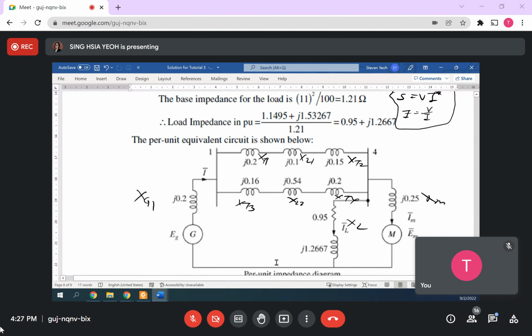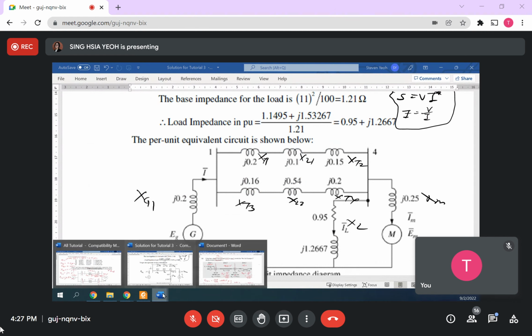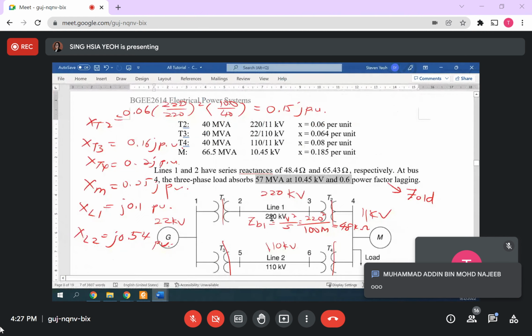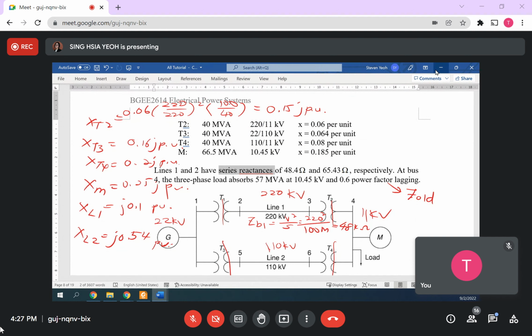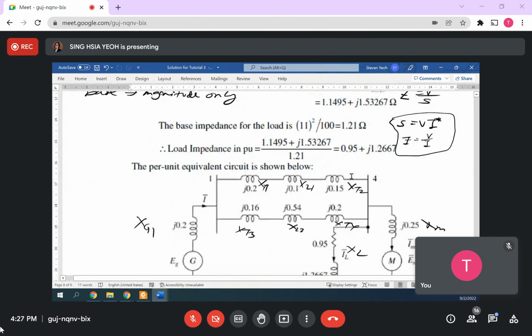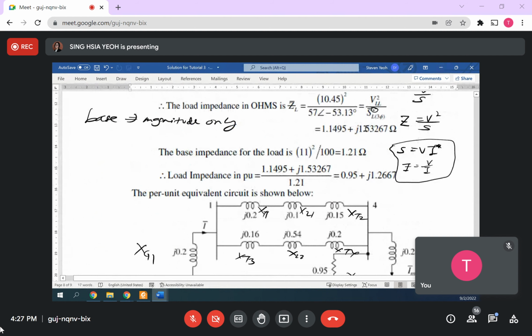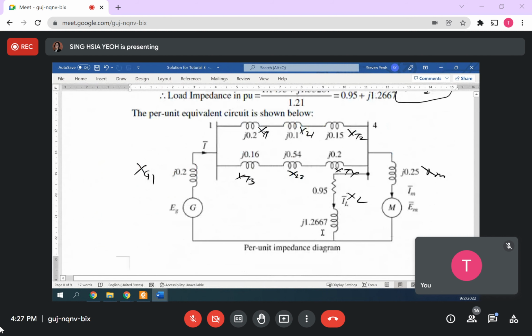Including the transmission line. Some students, when they do the transmission line, put it in ohms, like a real number, right? But actually it is series reactance, so it's actually X already. So my conclusion is everything you put J per unit, unless you have real plus imaginary, then your answer will have real plus imaginary. Other than that, just put J per unit. Okay or not?